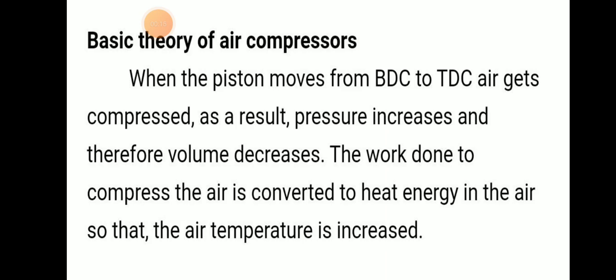The basic theory of an air compressor is that when the piston moves from BDC to TDC, from the bottom dead center to the top dead center, air will get compressed inside the cylinder. As a result, pressure increases and therefore volume decreases. The work done to compress the air is converted to heat energy in the air, so the air temperature increases. This is the basic theory of an air compressor.